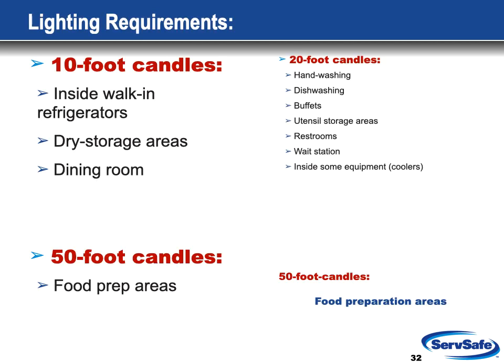For comparison, 10 foot candles is required for areas such as walk-in refrigerators and dry storage areas in the dining room. 20 foot candles is the requirement for places like the hand washing stations, the dishwashing area, buffets, utensil storage, restrooms, wait stations, and inside coolers. 50 foot candles is required for food prep areas.